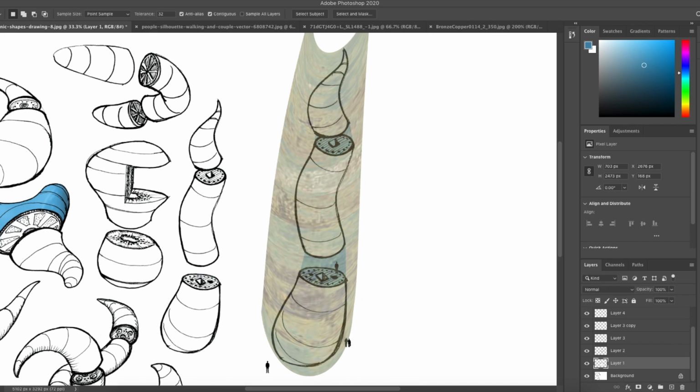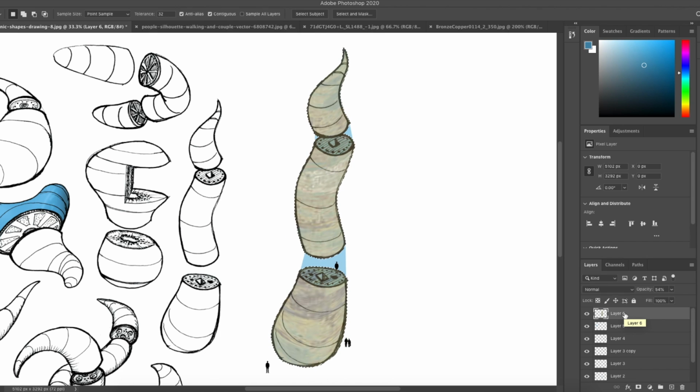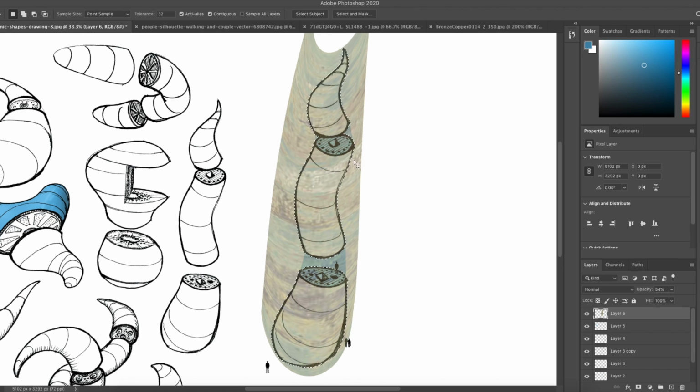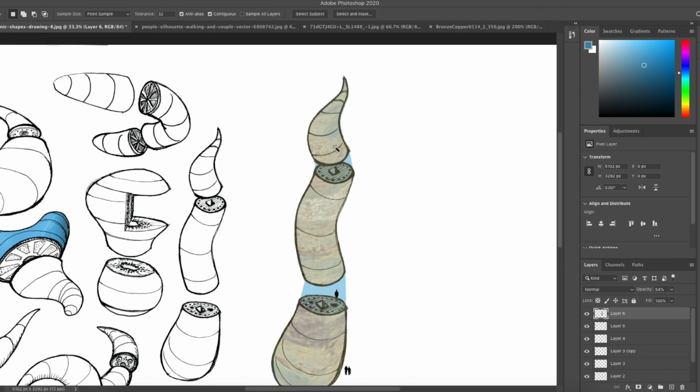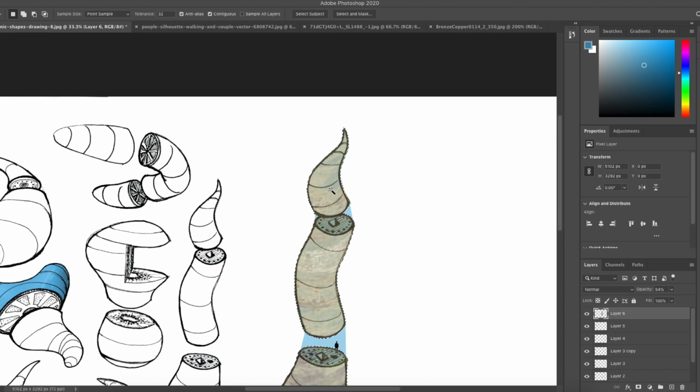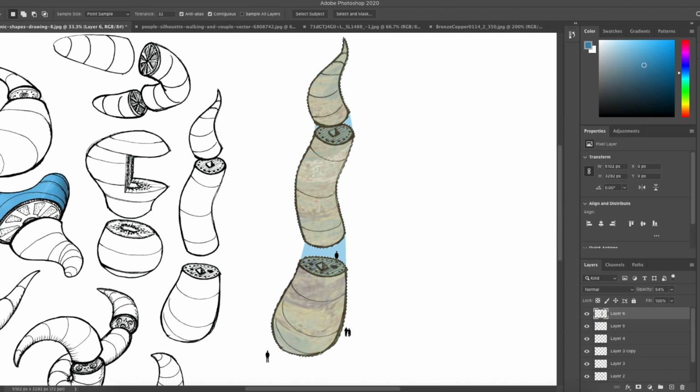So if I just use my magic wand tool, I'm just going to select these outside areas, press that, then press shift and select in there. What I've done is I actually selected everything other than this object. Okay, so everything else should be selected. Go back to my layer 6, hit the delete key, I can just delete that out. If that confuses you, by all means, just go in with your eraser and delete things. But I've now got that nicely wrapped around my building, like so.